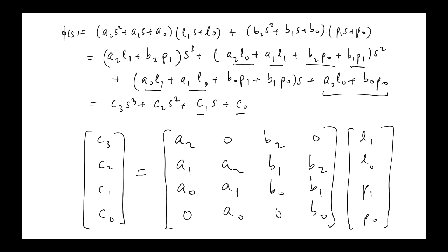All right, so this is just writing down a system of linear equations obtained by matching coefficients of some polynomials in matrix form. What you can see is that there's a bit of a pattern here. As long as you order the unknowns in this way and the knowns in this way, the first column here just consists of the coefficients of the polynomial A, the denominator of the plant transfer function, listed in order until we run out, and then we put zeros in, right?